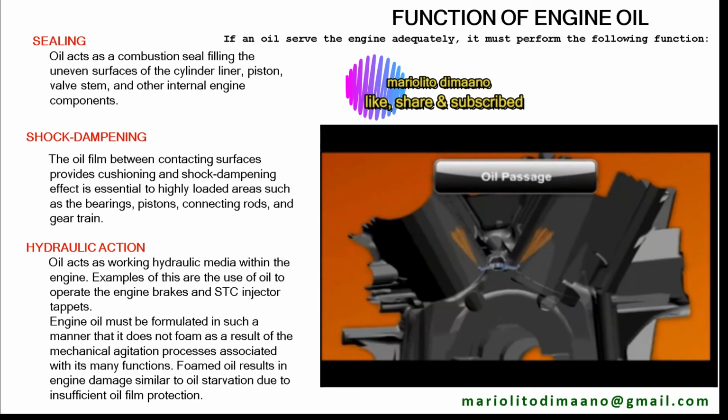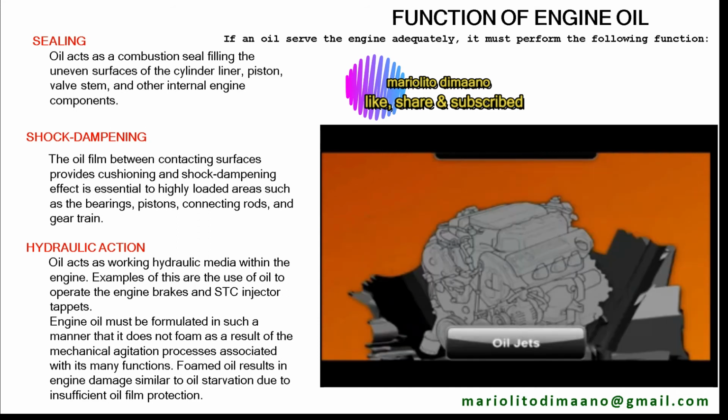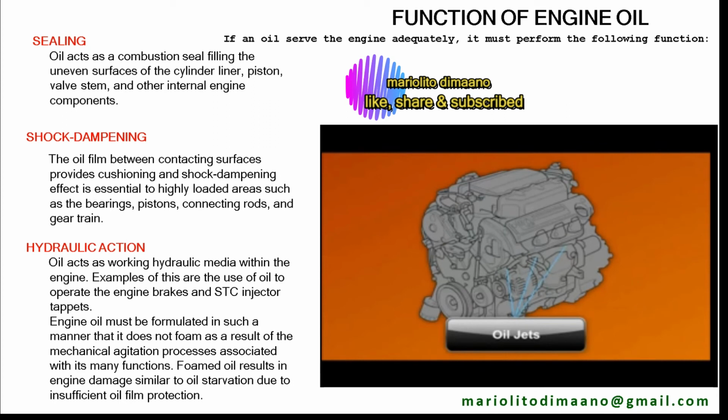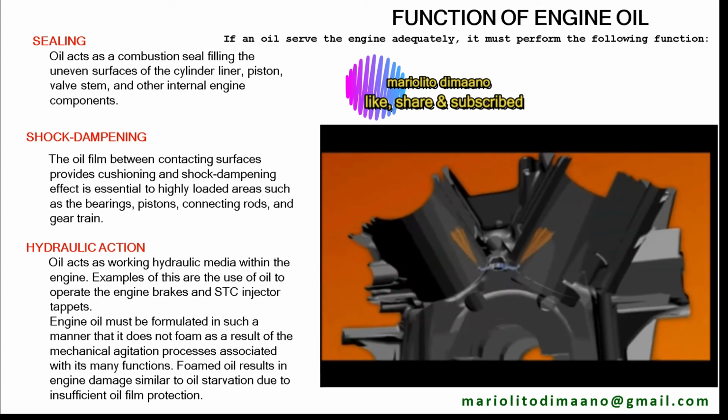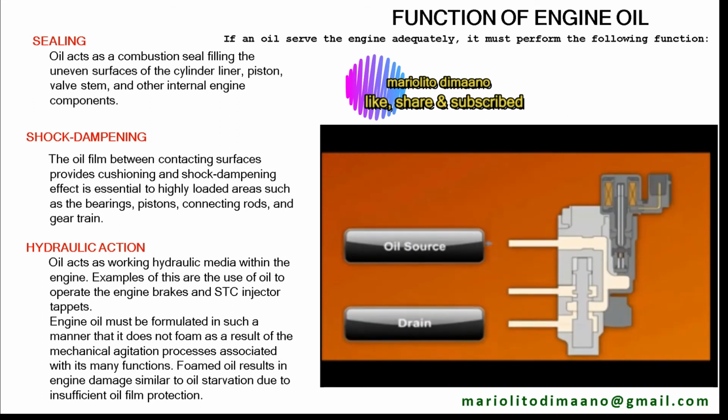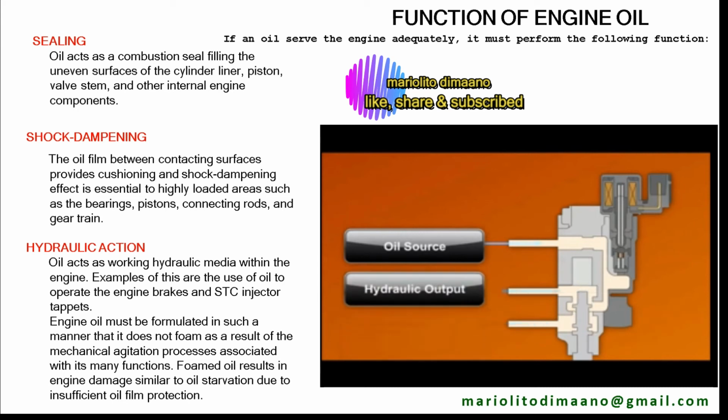A few oil passages end with oil jets, located on the block underneath the pistons. These oil jets spray oil into the cylinder to lubricate the cylinder walls and cool the piston bottom. The final system component is in the cylinder head, where oil passages feed oil to cam control solenoids. When energized, the solenoids hydraulically operate VTEC pistons or a VTC actuator.